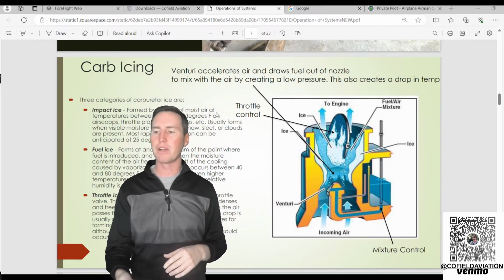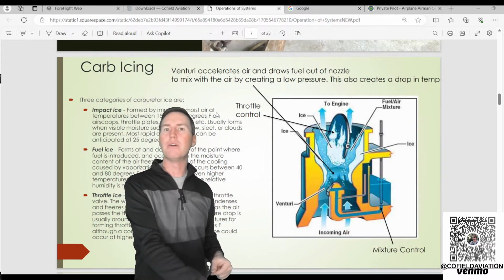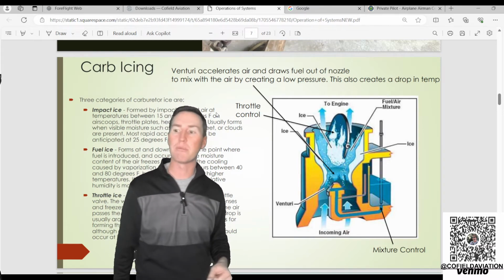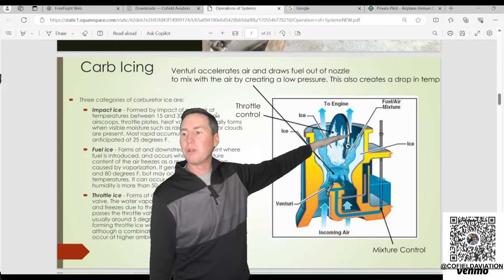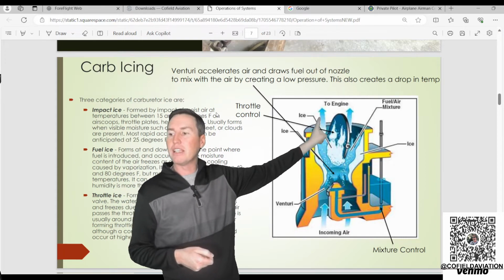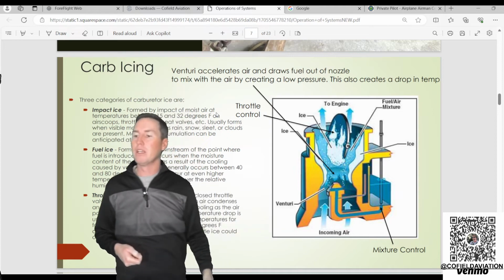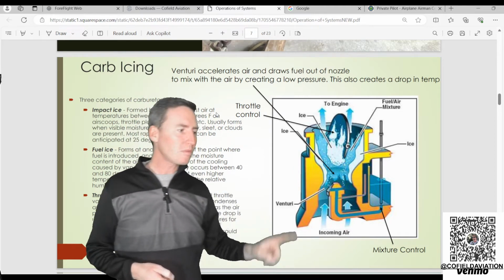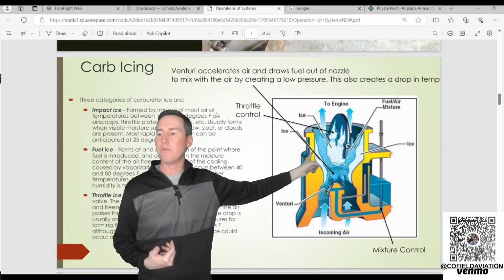Well, you probably think, oh, my friction got loose or something with the throttle. So you go and you push it in to no avail, right? It's not increasing the power. But what's happening is it's the same thing as if we were closing this butterfly, like closing the throttle: we're restricting the fuel air ratio to the engine. So it's getting less and less power. So that's where we would then pull carburetor heat to melt this ice.